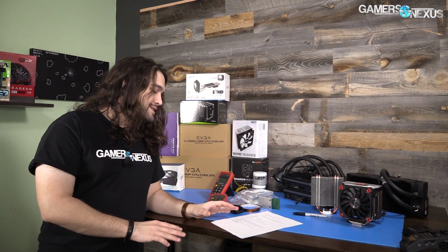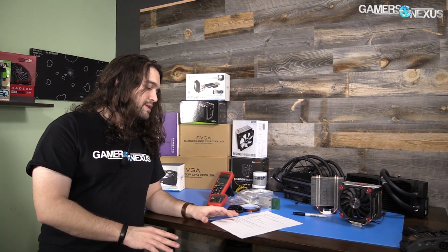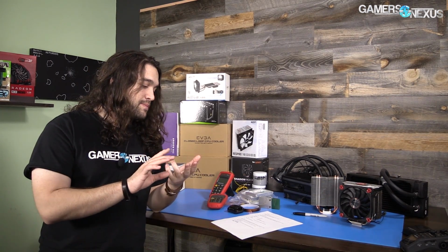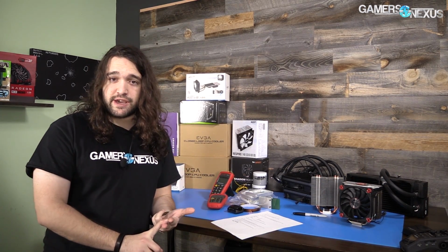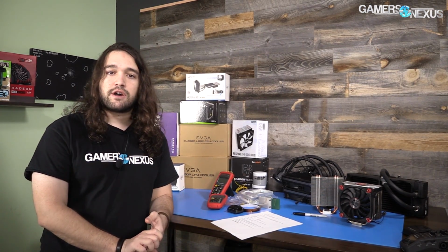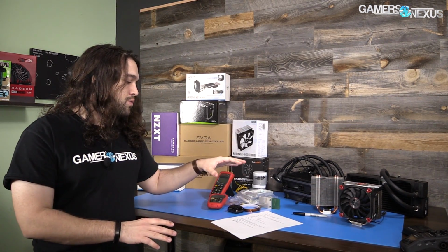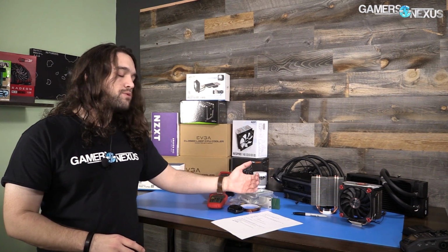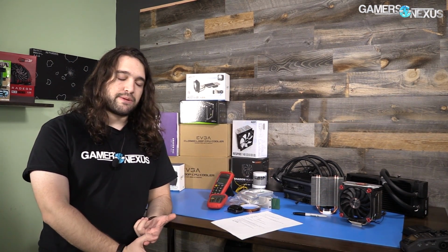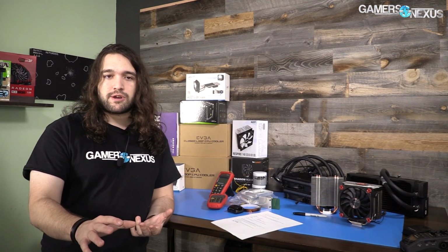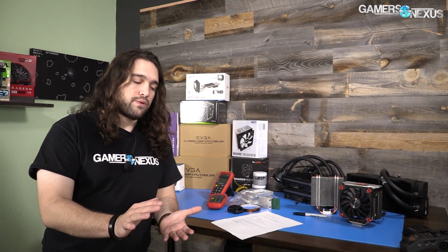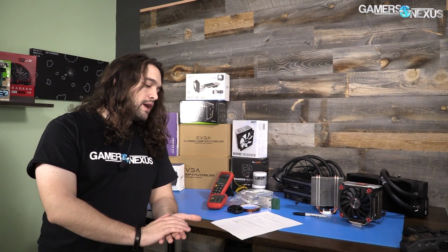The test environment, there's a few things that really matter here. One is ambient temperature, and we've talked about that in the past. Another one is the BIOS settings. Those are really critical, probably more than any other single aspect of thermal testing. So let's go with ambient temperature first. Room ambient, you want to control the temperature in the room as much as possible. If a thermal chamber is not available, we don't test in a thermal chamber, but we've validated in one, so the methodology is known good. And that's really all we needed for this type of testing.